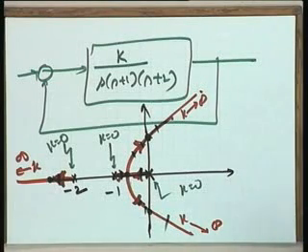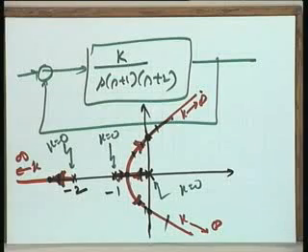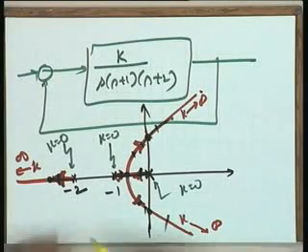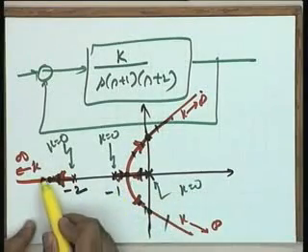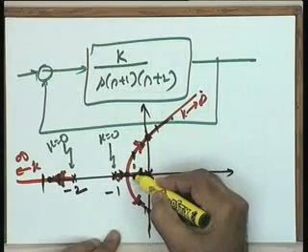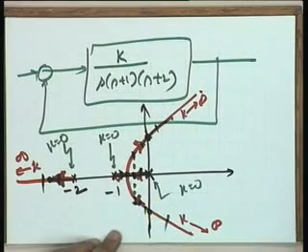Okay? Yes, please. The third root does not affect the transient performance, the one which starts from -2 and goes to infinity. Why? Does it affect the transient performance when you are deciding the design of the system? Yes, this we have discussed: the third root of a system, if it lies in the insignificant range, then it does not affect the transient. In this particular case, for example, I have not given you the numerical values, but when I take complex conjugate roots, this is the real part. Let us say it is -0.5, and let us say this is -3. Yes, it will not affect.